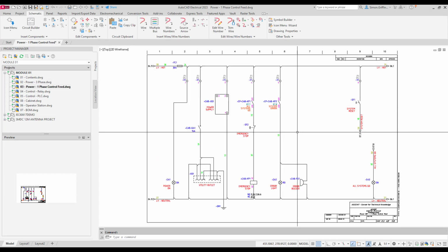Now I know that that symbol inserts successfully, I'm going to add that symbol into the Vault under the Common Electrical folder. Then I'm going to delete it out of my local workspace to replicate me being another user within the electrical team. And then I'm going to show you how Vault Eagle can help us synchronize that electrical data from the Vault back into our local workspace, so then my custom symbol can be used across the electrical team.